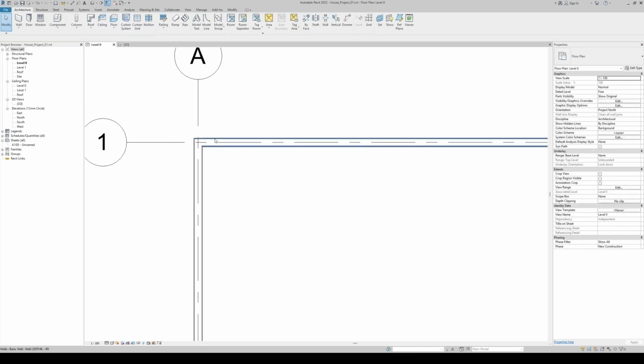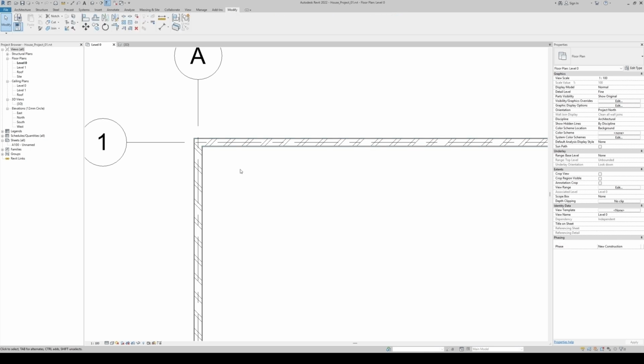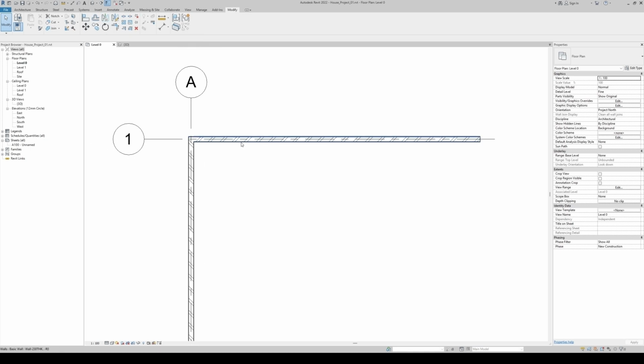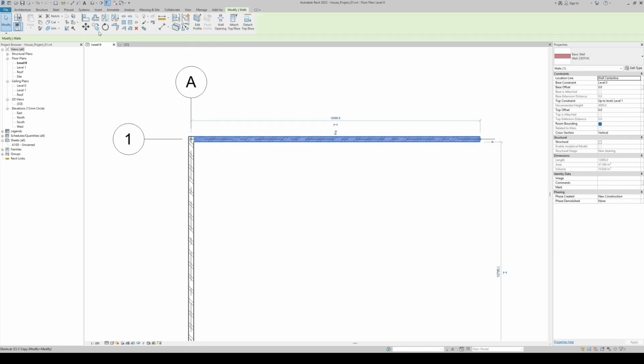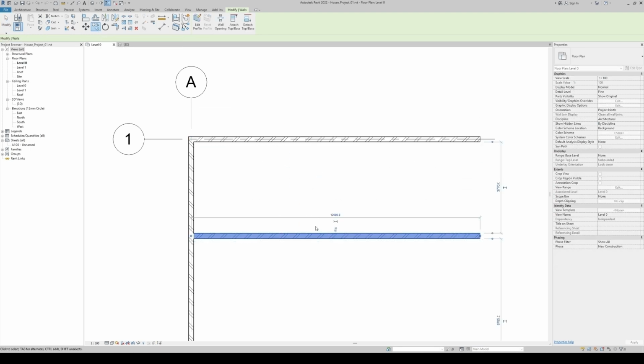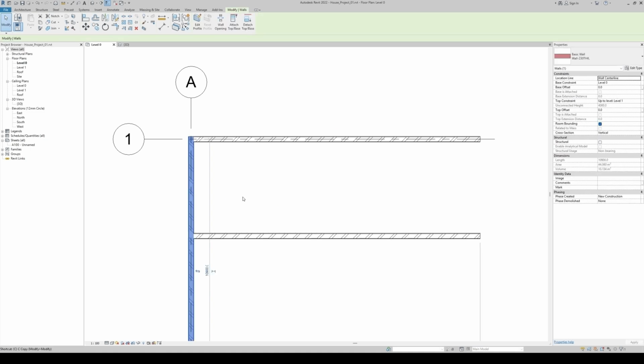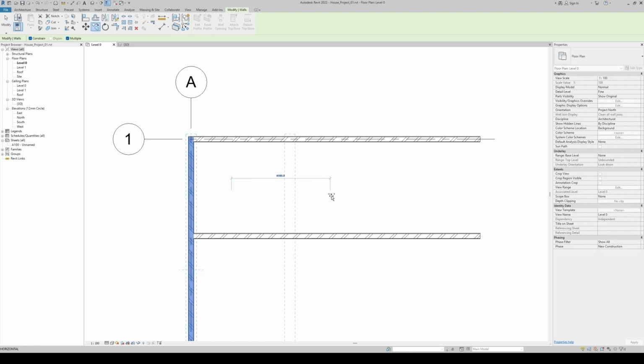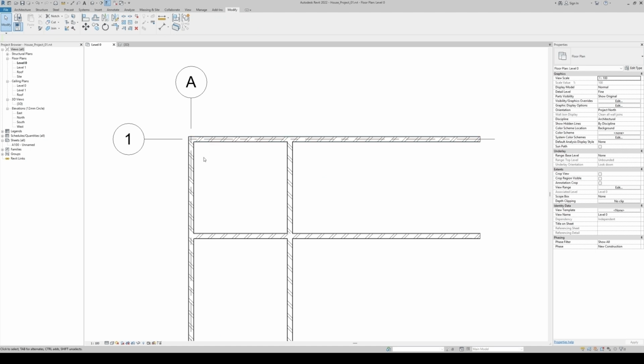And once you have a few of your walls modeled, you can go to the Modify panel and you can copy, move, rotate, align, and do a lot of modifying to your walls. So let us pick one of the walls and select copy and let us make a room. Hit escape, pick this wall, either go to copy or hit CO and just copy this room. So now we have a closed box which we can say is room 1.